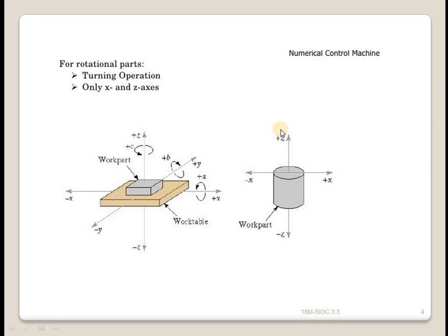The second and more common feature on modern NC machines allows the machine operator to set the 0 point at any position on the machine table. This feature is called the floating zero. The part programmer is the one who decides where the 0 point should be located. The decision is based on part programming convenience. For example, the work part may be symmetrical and the 0 point should be established at the center of symmetry.